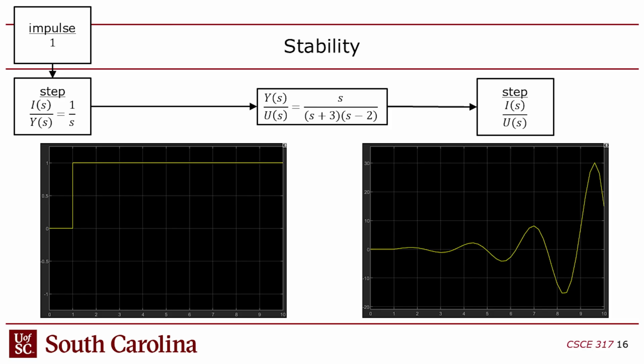Now, we're not going to do that in this class. In this class, I just want you to understand that there's stable and unstable, and we'll just use the transfer function to determine if it's stable. This is just for illustration. You guys with me? So if you had MATLAB, you could create this in Simulink and actually see what happens when you hit it with a step, right?